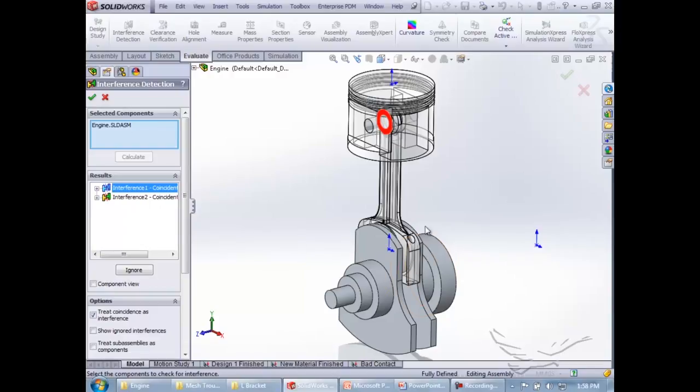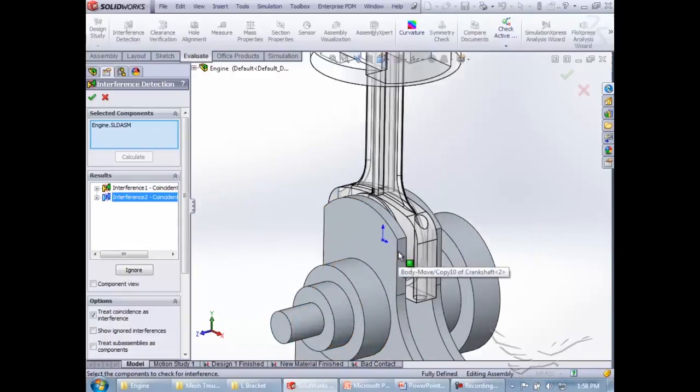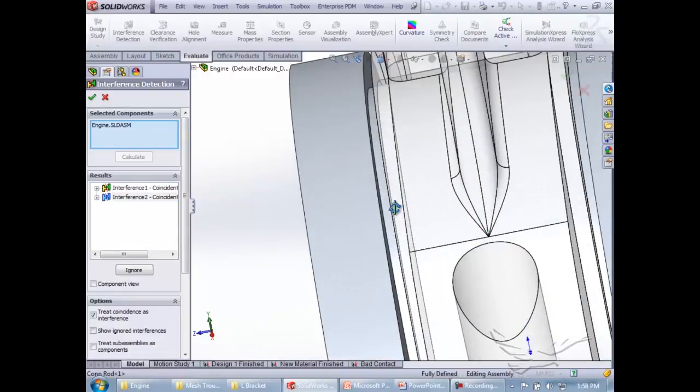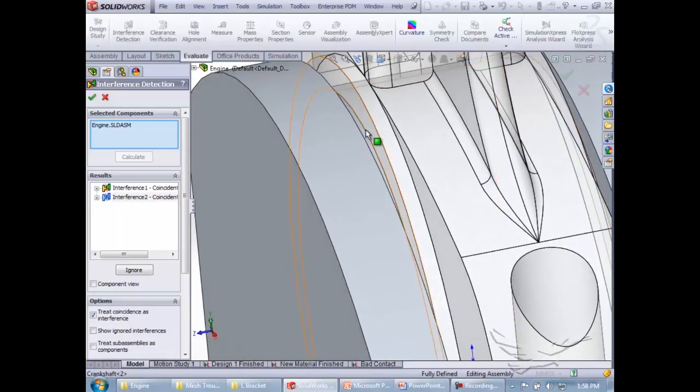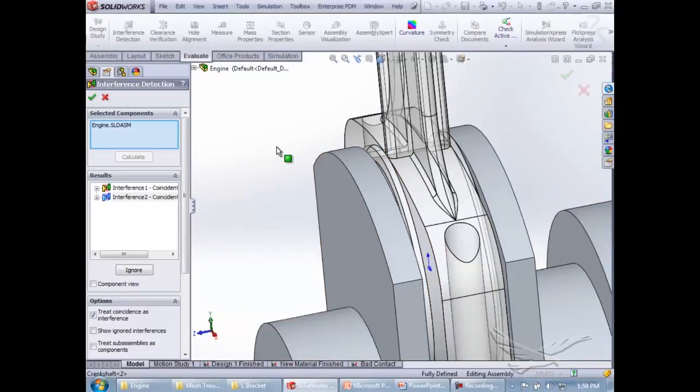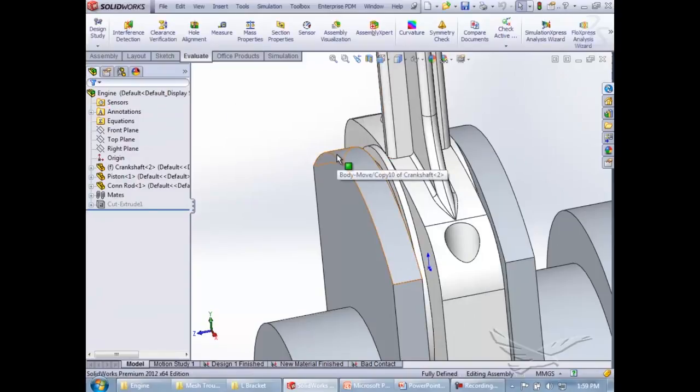Now, I intended for this whole bottom section to be bonded as well, but if you look, there's only two coincidents up at the top. That means that if we actually go in here and look, there's actually gaps from here to this sidewall, and also the OD of here and the OD of this inner cylinder. And so there's no touching, they're not going to get the global bonded contact set, and that's why this is passing through. So at that point I would either make a modification of my model to make sure they're touching, or manually add a contact set on those two specific faces.